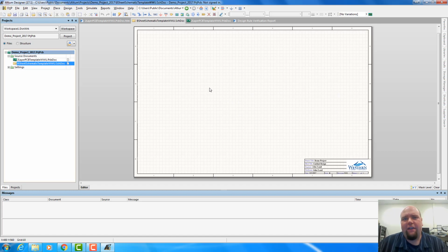So to start, we have to have a way of making a connection to our board. There's lots of ways to do that. We could have a ribbon cable connecting to the board. We could have a USB port. We're going to do something simple this time. We're just going to do a header. So we're going to do a standard 0.1 inch spaced header connection for this board.